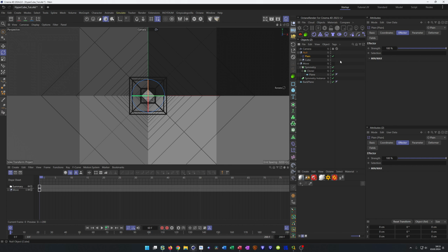So good. First thing I need in the parameter, I need a rotation, and I make here quite a lot. So on this one, I can change all three together. Say 1440 here, and now hold my Control key and click enter, and you see, so you change everything together.